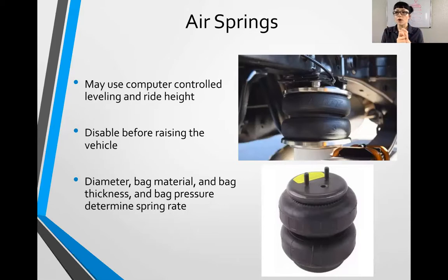Some use it for comfort, others for the adjustability of ride height. Another thing, most springs, if you're adjusting ride height, you are also adjusting your spring rate. And airbags are very much the same. So airbags do have different spring rates. They're actually really hard to calculate because it changes as you fill and deflate the bag, but they also change on the thickness of your bag material.